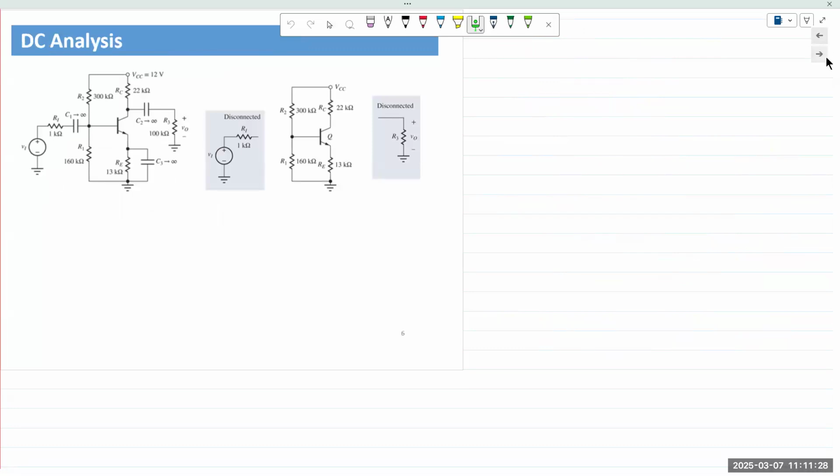So we looked at amplifier circuits, right, at the end of chapter 4, and then we looked at designing an amplifier. Now, consistently, I stated that we set up our BJT or our device to operate at a certain point in the active region to function as an amplifier. And that is performed by the DC voltages that we apply. And then on top of the DC voltage, we apply an AC signal, right? That's how it functions as an amplifier.